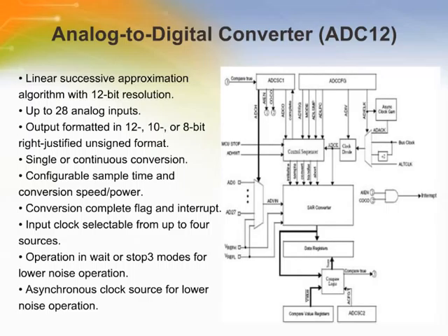When the conversion is completed, the result is placed in the data registers ADCRH and ADCRL. In 10-bit mode, the result is rounded to 10 bits and placed in the data registers ADCRH and ADCRL. In 8-bit mode, the result is rounded to 8 bits and placed in ADCRL.